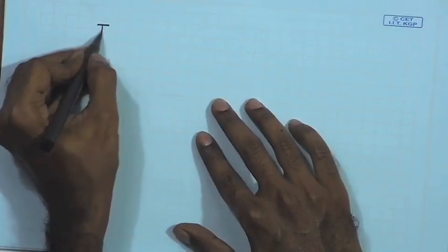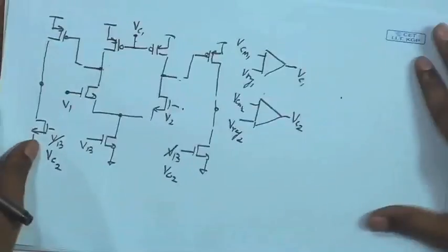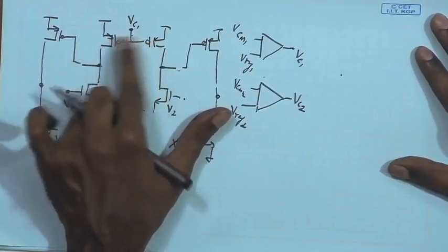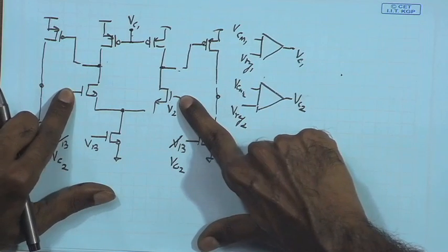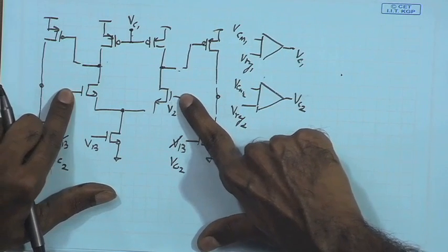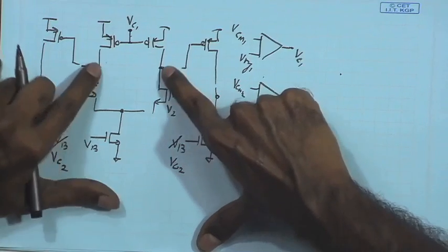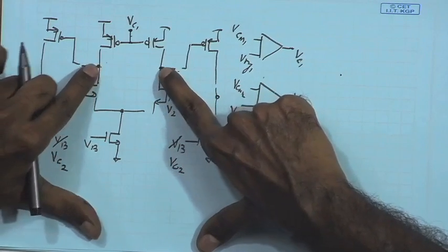So, we know that for a single differential amplifier stage, when we arrive at the common mode half circuit, we will be basically combining the input devices together, assuming that the input voltage is the same, because if the input applied voltage is the same, the common mode value, the output DC point will be exactly the same. As a result, we can tie them together.